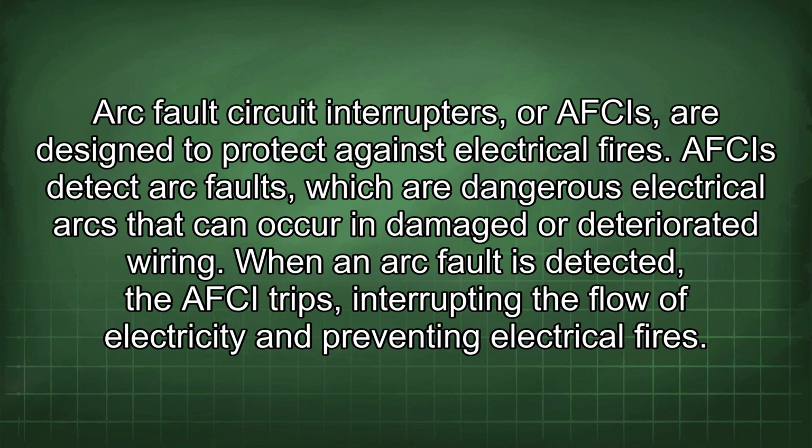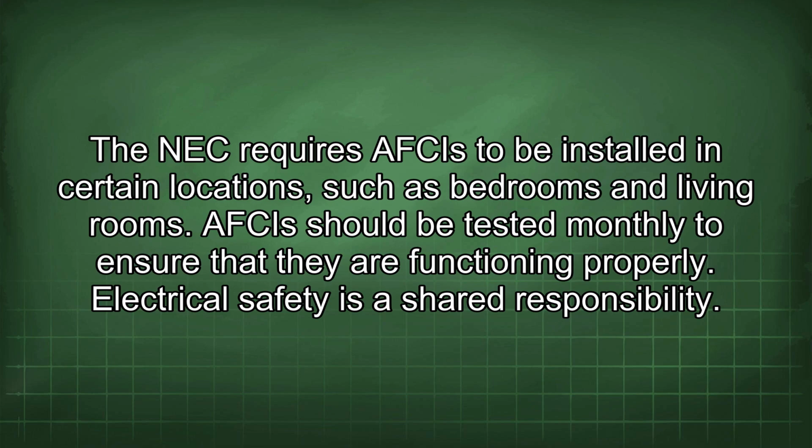Arc fault circuit interrupters, or AFCIs, are designed to protect against electrical fires. AFCIs detect arc faults, which are dangerous electrical arcs that can occur in damaged or deteriorated wiring. When an arc fault is detected, the AFCI trips, interrupting the flow of electricity and preventing electrical fires. The NEC requires AFCIs to be installed in certain locations, such as bedrooms and living rooms. AFCIs should be tested monthly to ensure that they are functioning properly.